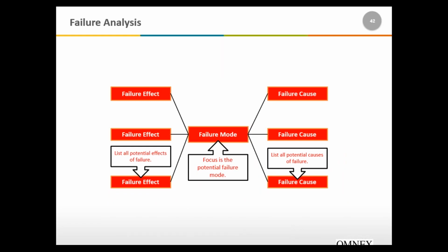Yes, and so really this is the failure net. Once we get all the failures, we can now get the cause and effect relationship. The higher level failure modes eventually end up as effects of the focused level. So in order to build this, I take a look at my focused level, and I take a look at a failure mode from there and ask, what are the effects of this particular failure mode? And then we go to the right and say, when we're looking at how, what are the causes of this?